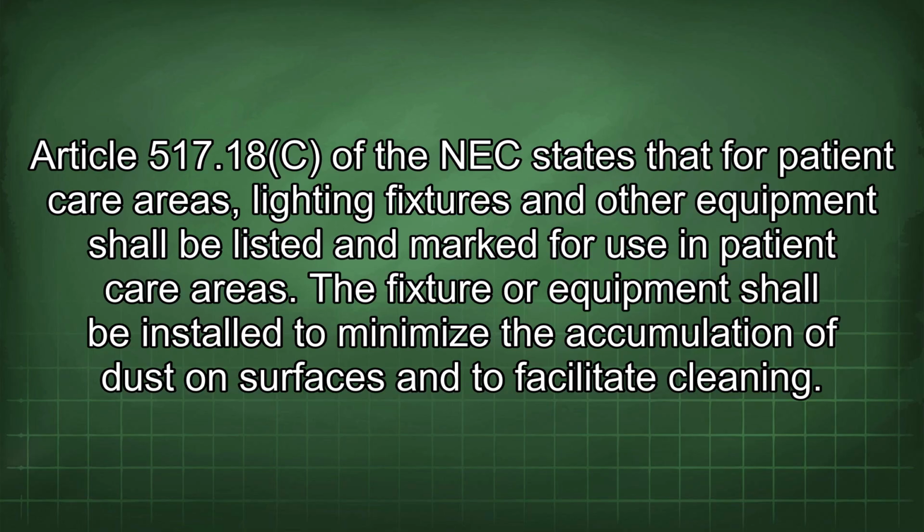Article 517.18(C) of the NEC states that for patient care areas, lighting fixtures and other equipment shall be listed and marked for use in patient care areas. The fixture or equipment shall be installed to minimize the accumulation of dust on surfaces and to facilitate cleaning.